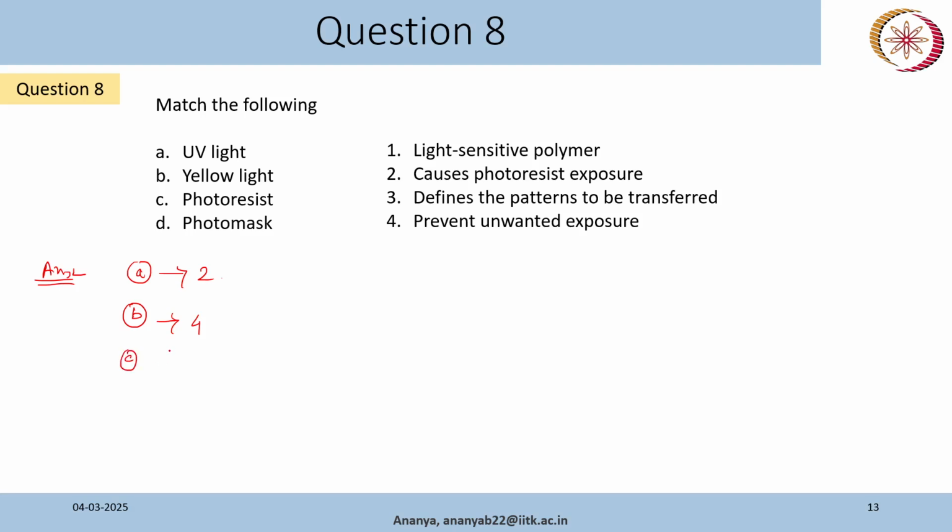I say this because I do litho in my lab, and sometimes we forget to maintain proper decorum, so that we don't expose our photoresist unwantedly. We turn off any white light source when we do litho in the litho room.